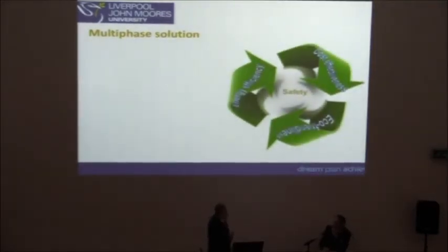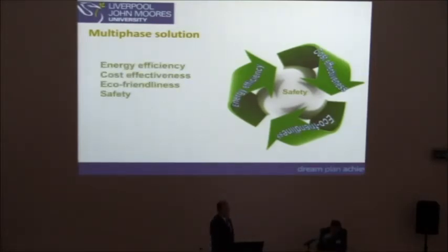So we have a multi-phase solution when using cold mix with waste material. It is energy efficient; there is no need for heating. It is cost effective because wastes are free and there is no need to buy anything, and it is eco-friendly. There is no CO2 emission, and we will save the natural resources. In terms of safety, it will be safe for the workers who mix and apply the mixture.